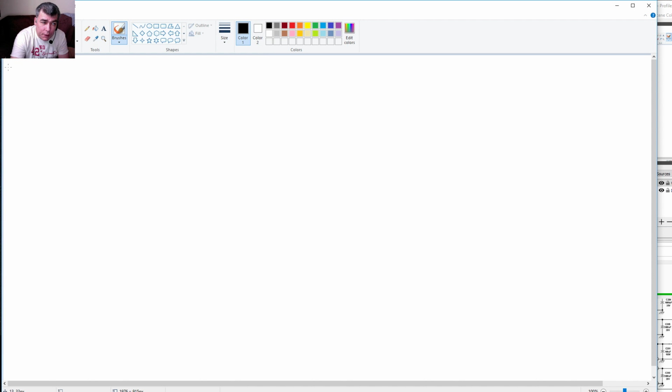So here we have the DC jack, yeah? We have the middle pin and we have the round connector. This is ground. I'll not draw the ground because ground is everywhere. And this is plus. Here is 19 volts. That's plus. After that you'll probably have some resistors, some fuses, but it's not important. I'll not even draw those things.